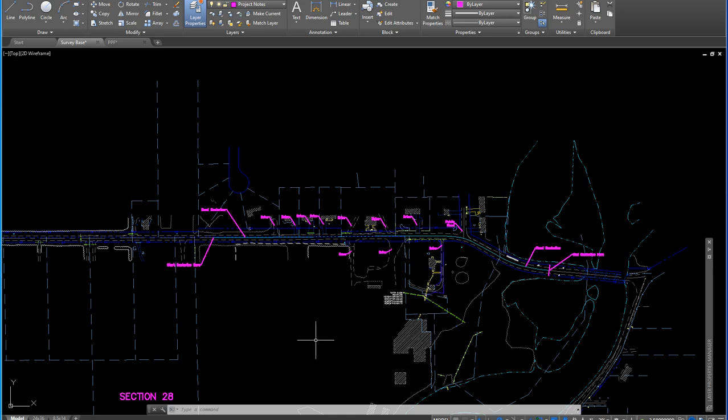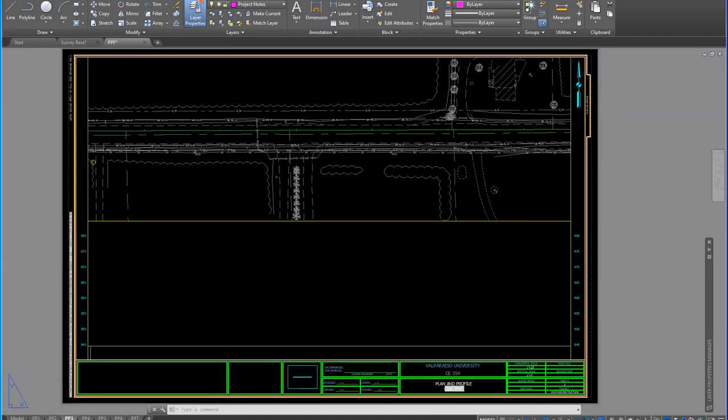And you're going to create a viewport, and you're going to show a portion at scale 1/20 of the road and your driveways. And then you're going to make another layout tab, another sheet, just to the right of it, and you're going to show another portion. And then you're going to make another sheet, and in the viewport, you're going to see just to the right of what was in the viewport for the one before it, and so forth and so on until you get down here. That's exactly how we build a sheet set. So you're going to make sheets as they come all the way down. I've got an example of that. Now these sheet sets load slow.